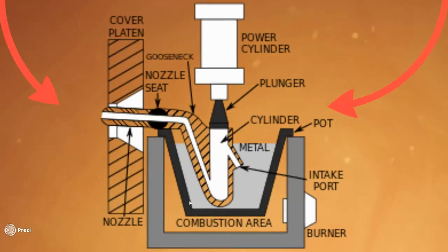And that was a cold die casting. Now you also have the hot die casting machine. This is hot die casting because your injector is actually in the metal, so your injector is going to be considered hot. Now keep in mind that a hot die casting machine can only cast metals with low melting temperatures. All right, I know that seems kind of backwards, but that's the way it is, and that's just because the nozzle is buried and embedded into the molten metal.